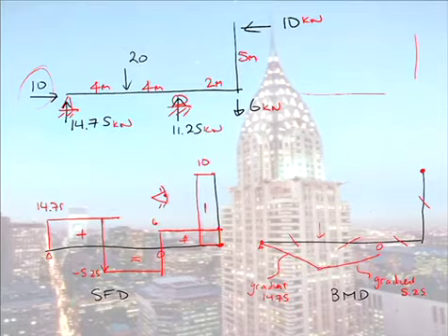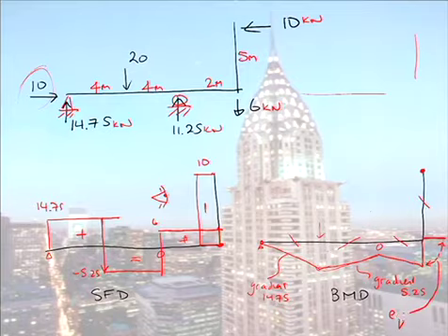And this is where you panic and go, oh, I'm not sure what I'm doing. No, I know I have to come down again. My slope is downwards. So I slope down. I haven't put values on this yet. And I just join it up to 0 as I do. Going round a corner, if that's on the outside, that has to be on the outside. Because we know going around a corner, they're either both on the outside or they're both on the inside. So those two values are equal. And we know we have to end up at 0 on the top, and this is actually sloping the right way.